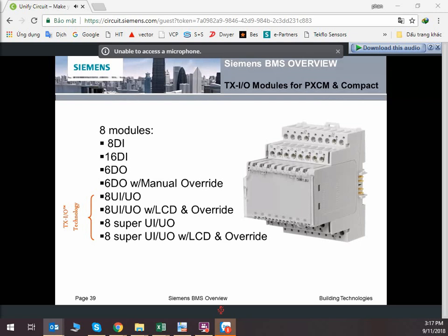You'll notice that the PXC Modular and PXC Compact, our ALN controller, do not support the triad relay, the relay for lights and relay for blinds modules. Those modules, only PXC3 are supported. Okay? Just take notice. And you'll notice that super universal modules here are not supported by PXC3. Okay? PXC3 cannot be used for super universal modules.